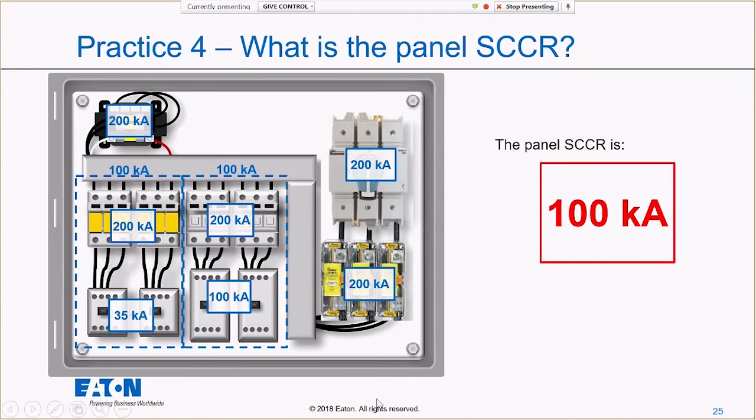That's one animation short. So that's with my non-fuse disconnect, power distribution fuse, fuse block, and fuses in all my branches. Of course, I'm going to get a high panel short circuit current rating like this. In this situation, if I'm above 200 amps for my main, I think this is my best solution today. But Bussmann has actually come out with a better solution.